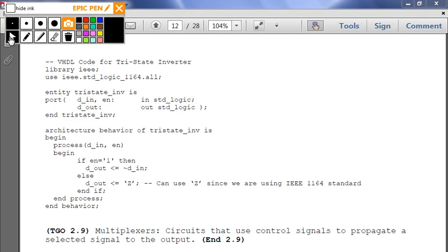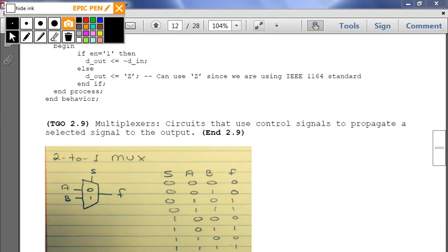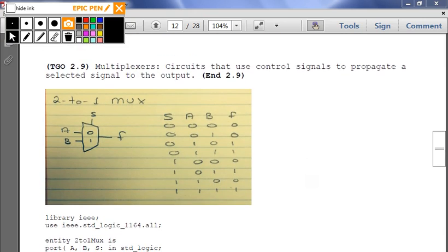So we need to know that table as well. Yeah, well, okay, let's go over the truth table, where you can actually derive it by understanding the concept. If I give you a tri-state buffer, for example, the purpose of the tri-state buffer is to propagate the signal when the enable is 1, right? So without even looking, we can derive the truth table. What are my 3 values that I want? In, out, and enable, right? So when enable is 0, Z.